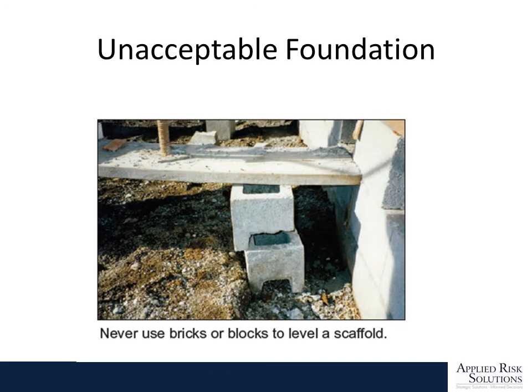This is an example of an unacceptable foundation. You can't just stack up some broken concrete blocks, or any kind of concrete blocks for that matter, stick a mud sill on it, and then level it as best you can with the leveling screws. That's an unstable foundation. You should never do this.